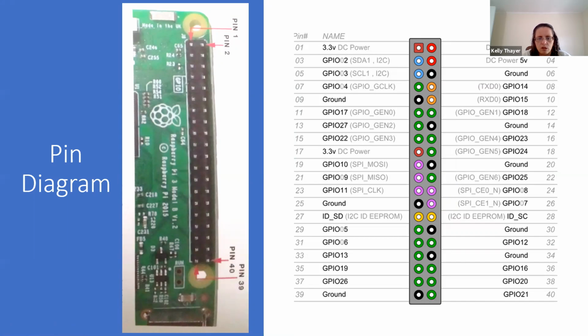It's important to note that there are the pin numbers, which are just their index counting from 1 to 40, and there are also these name indices, which are not necessarily contiguous because they're interspersed with a variety of other things. You'll notice that you'd need to power this, so you're going to have these power positions here. That's 3.3 volts, and we should also have a 5 volt available, which is here on the other side. So different voltages are available.